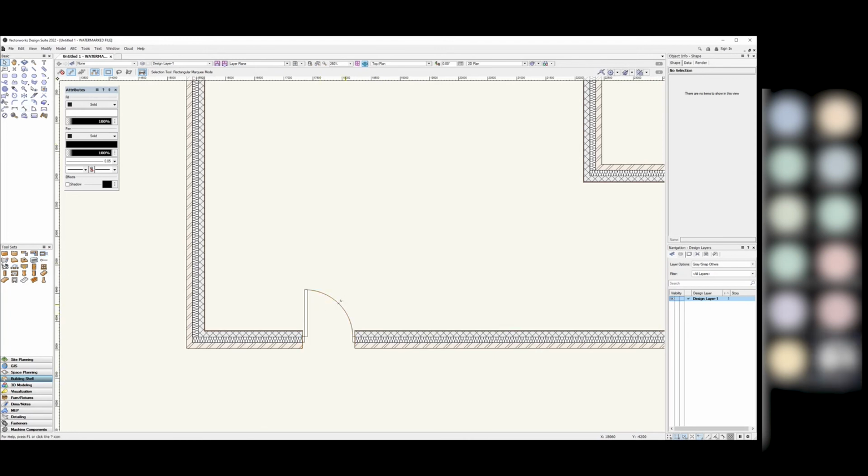So I've just placed in that standard door, really basic door for now. But what if I didn't want that horrible, ugly basic door? Well, it's the exact same thing as when we chose the walls. I can click on the door tool. I could choose the door style.